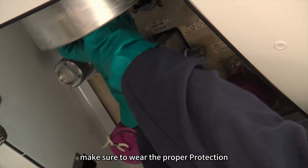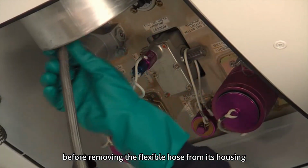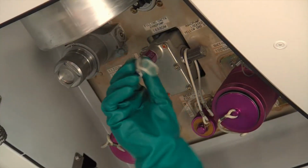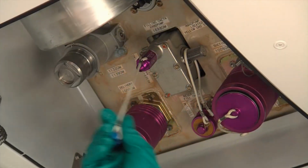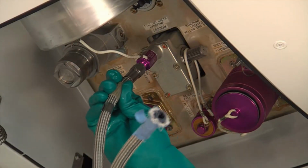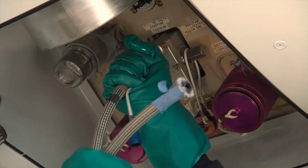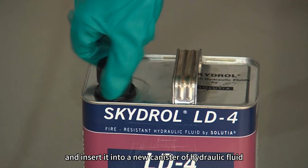Make sure to wear the proper protection gloves and goggles before removing the flexible hose from its housing. Connect the hose to the hand pump and insert it into a new canister of hydraulic fluid.